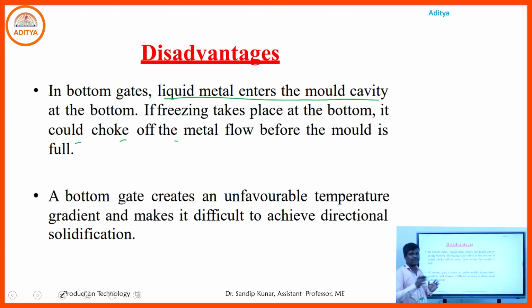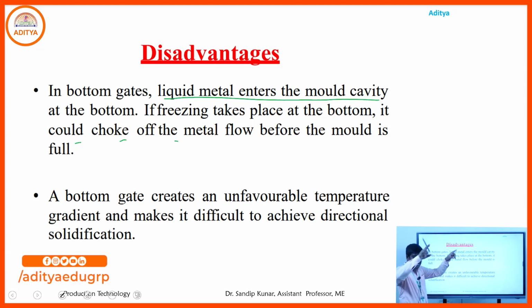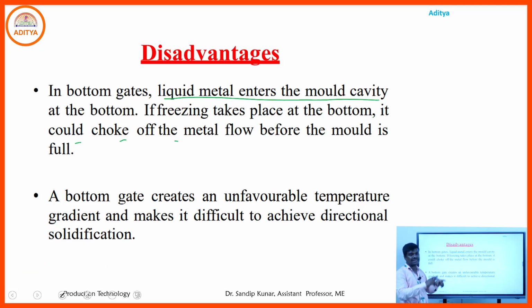Means sometimes due to freezing in the mold cavity, the entire inside surface of the particular mold cavity does not fill up properly. So always you maintain the flow in the mold cavity, means it will take the total shape of the mold cavity. So the product will be a defect free product.